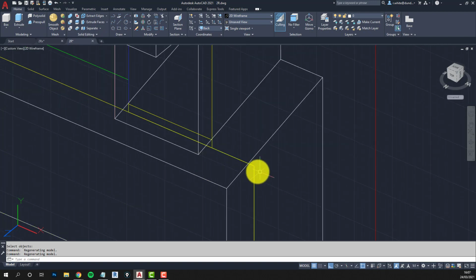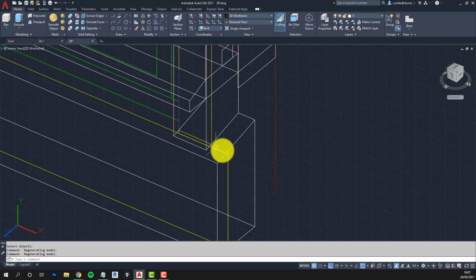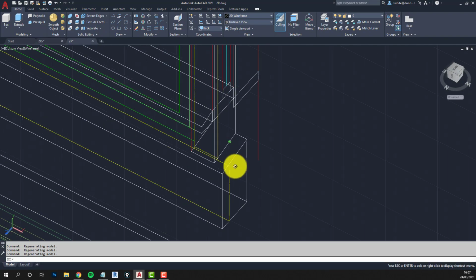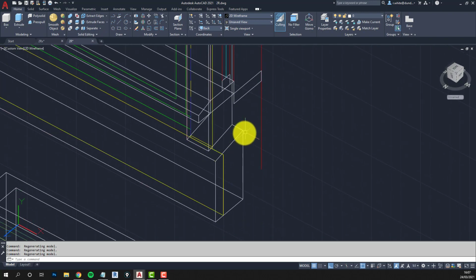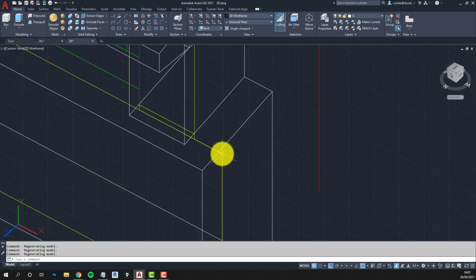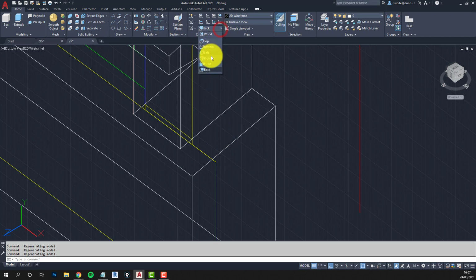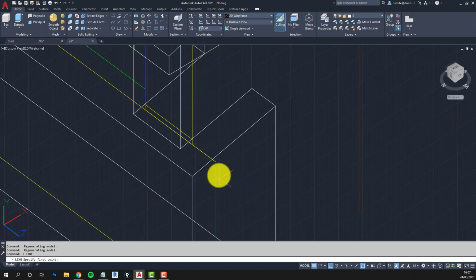Okay, so using the front UCS again, we need a box that's this shape. Okay, but it needs to be a little bit higher. It's where the wall would be cutting through. So it's more the projection of this line up to this one. So that's a little bit tricky. We need to go back to the left UCS for that and draw a line up here, a line along here, and then trim those to each other to find where we draw our box.